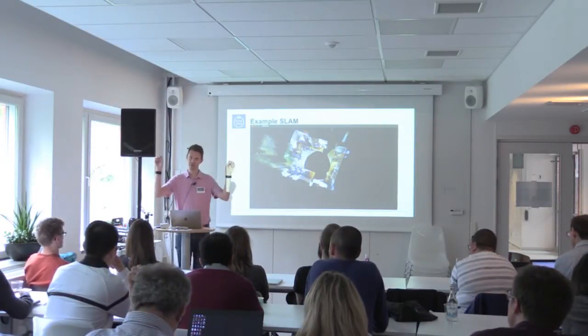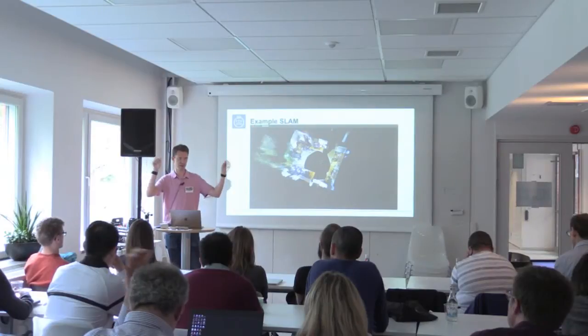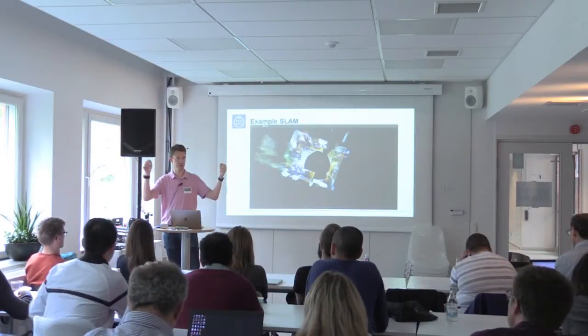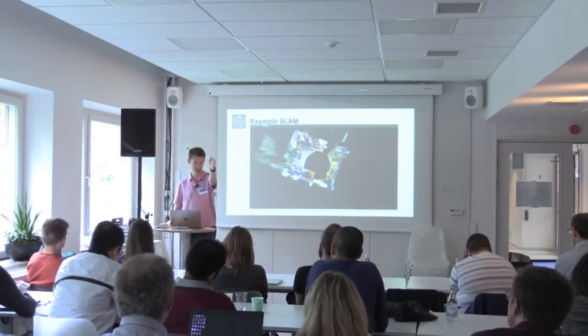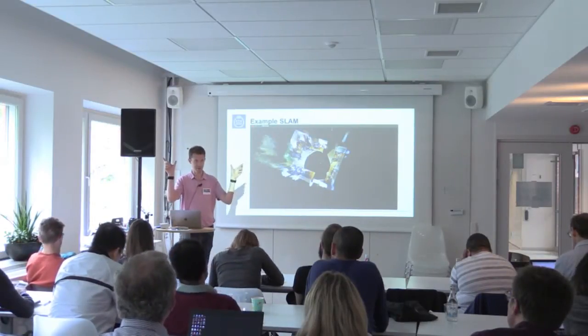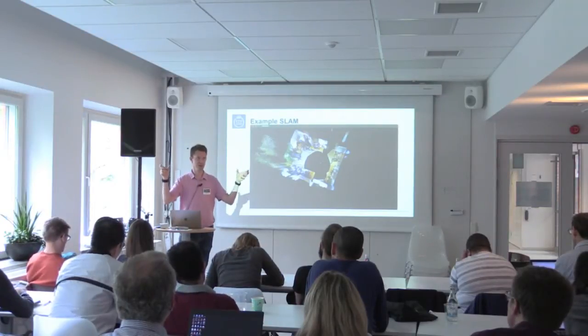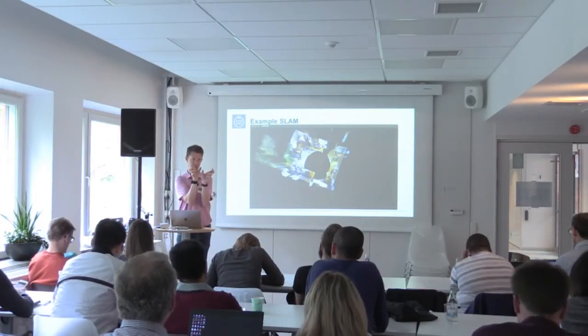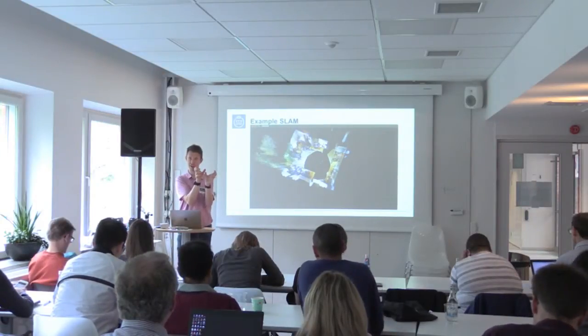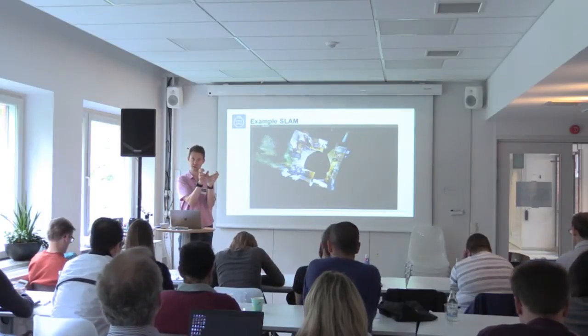Yeah, and if you put the cameras further apart, it becomes more difficult to find the correspondence between the left and the right image, and this is needed to be able to calculate the distance. So if I want to calculate the distance to the door over there, I somehow have to find the pixels in the right image and the left image that correspond to each other. And the closer I move the cameras, the more similar the images will be, and the easier it will be to find that correspondence.